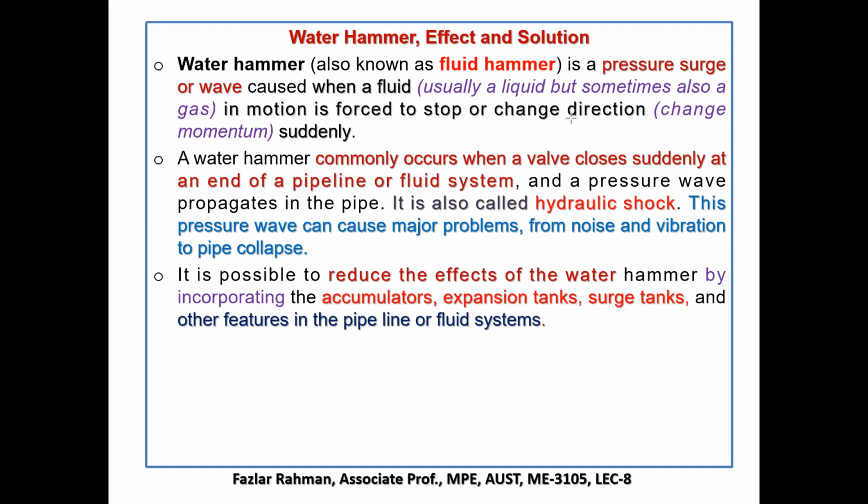That means your momentum is changing. Say you are driving your bike at a certain speed, and suddenly you make a hard brake. So your change of momentum is very high, because the final momentum is zero, velocity zero, and the initial momentum is m times v. So if you change the direction of the fluid, or suddenly stop the fluid in a flow, then there will be an increase of pressure.